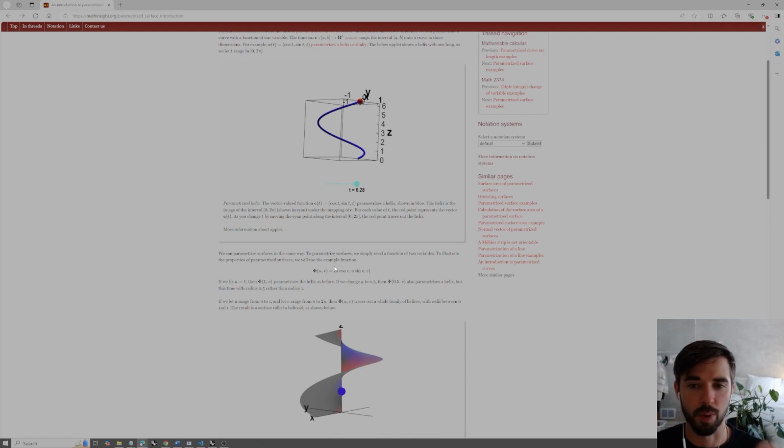We're feeding in both of those values, just like we did with one singular dimension, mapping a parameterized curve. This time we're mapping in these two dimensions, creating rows of curves that then can be used to define a surface. So u times cosine of v is x, and then u times sine of v is going to be the y, and our v value is just our z.